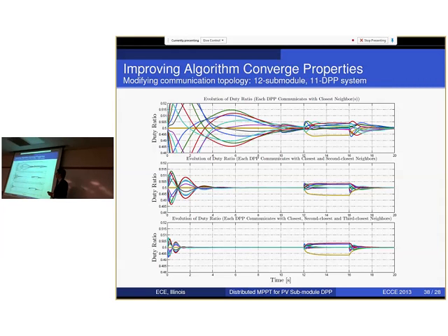Will this respond too slowly? Well, the thing is, insulation changes happen very often during the day, but communication failures probably happen at months interval. So even if you are reacting a little slowly to communication failure, it's still going to be okay because it happens so rarely. You are not really losing much power because of that.